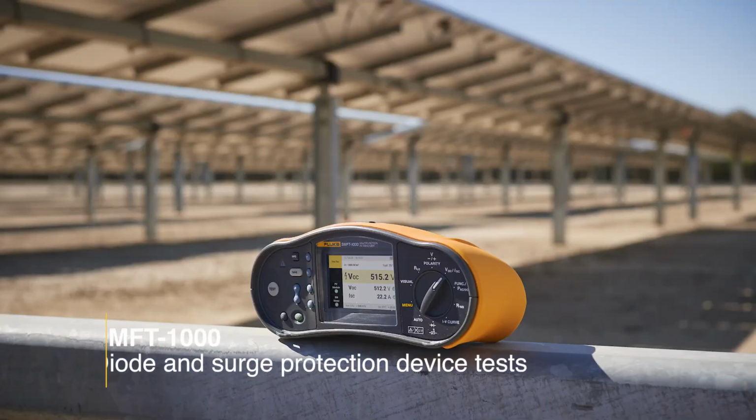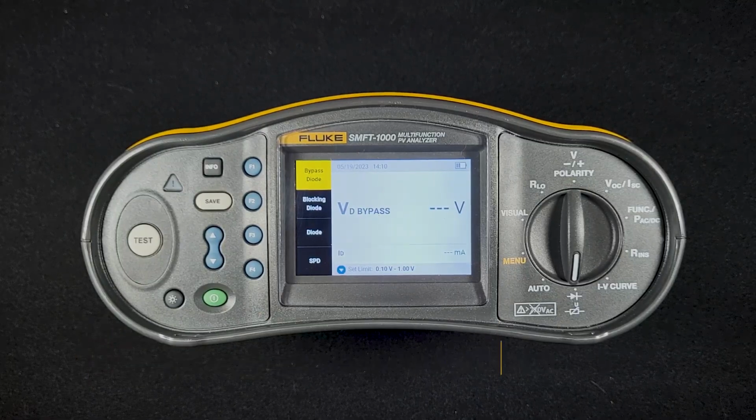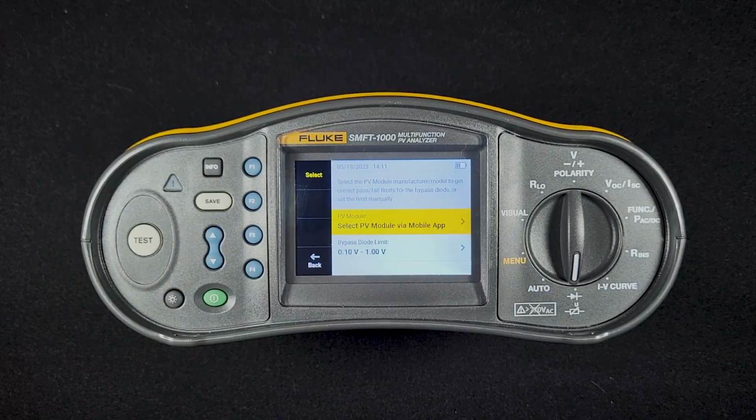We're going to look at the diode and surge protection device tests in the SMFT-1000. When you first switch to this test, the first thing you'll see is the bypass diode test. In this one, we can test bypass diodes to ensure that they're meeting their manufacturer's ratings. We can hit the down arrow and set the voltage limit. We're going to need to know the data from the bypass diode manufacturer or the PV module.